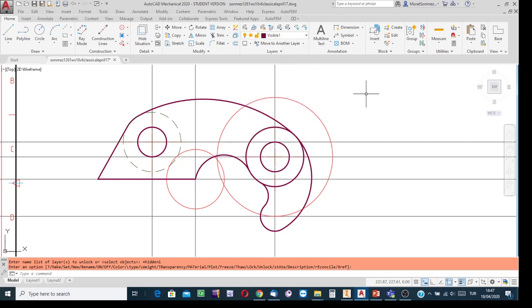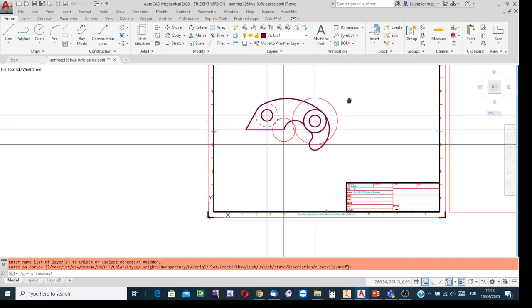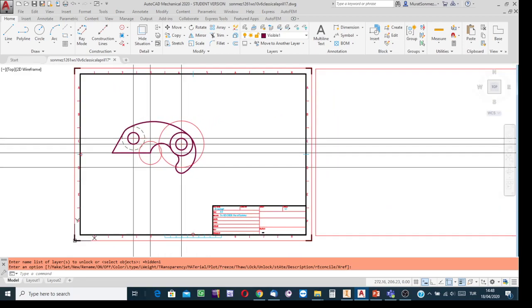Otherwise, when you move the projection to a different place, you're going to see that the hidden circle couldn't be moved. You know, the move process is cut paste. These are editing processes. Editing processes are all not applicable on the content of a locked layer. So unlock the layer, and thereafter you can apply the editing process.